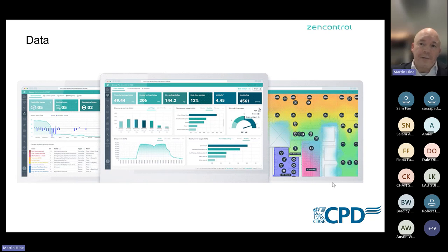So really health monitoring, status of lamps, reporting individual control gear, statuses, on-off statuses, dim levels, lamp failures, and ballast information are all standard requirements from a lighting control system. Obviously, error reporting, predictive maintenance. These are things that the FM requires, and really with DALI 2, you get far more enhanced information from the network of devices,